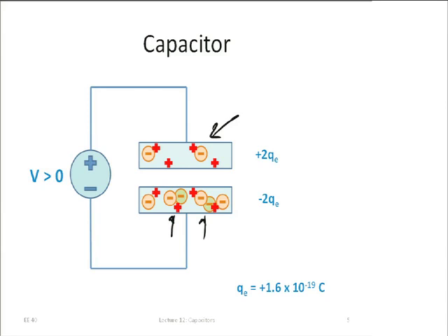Consequently, totally, we have two more positive electron charges in the top plate. And where did they go? Well, they went to the other plate here. Here, suddenly we have 4 protons, but we have now 6 electrons, and so altogether we have a negative charge there. Notice that the charge neutrality still holds for this entire device.